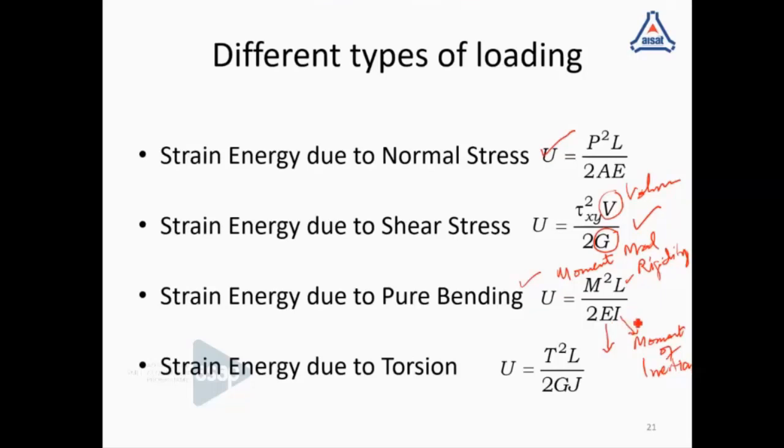Moment of inertia I, and EI is also familiar to you. So this expression can be used to evaluate strain energy in the case of a problem which involves only pure bending. Only a moment is applied.